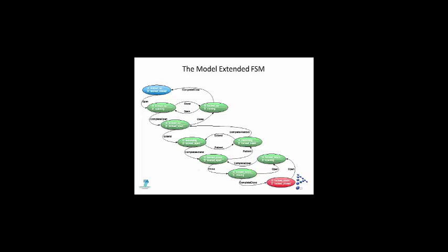And so initially you start down here, gears locked down. You're on the ground, gears locked down, doors locked open. There's a command that's issued, abstract level is open, you move to the state of opening. If nothing else happens, you can complete the open, then you can retract, and eventually you'll get to a point where you have the gear locked up and the door closed. Now already you have a notional abstract state machine for the system, and when you test, you want to cover these arcs. This is an untimed abstraction.